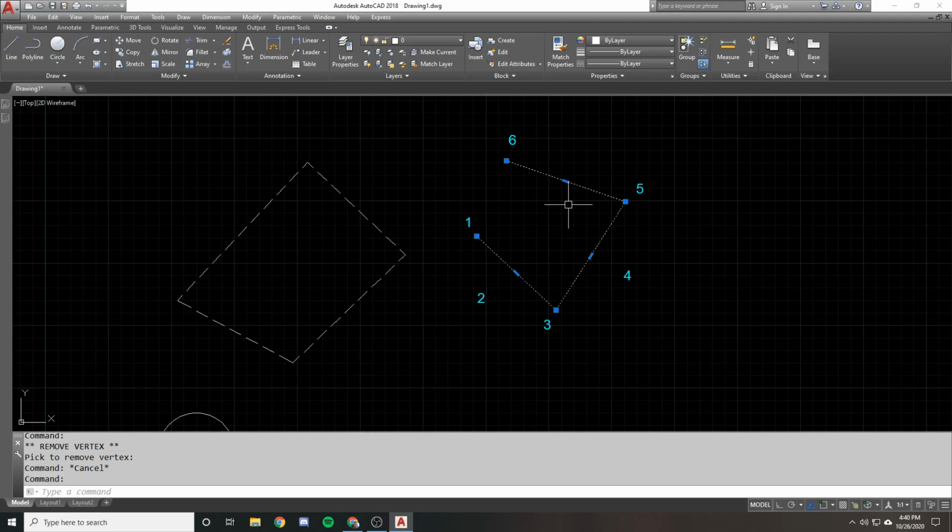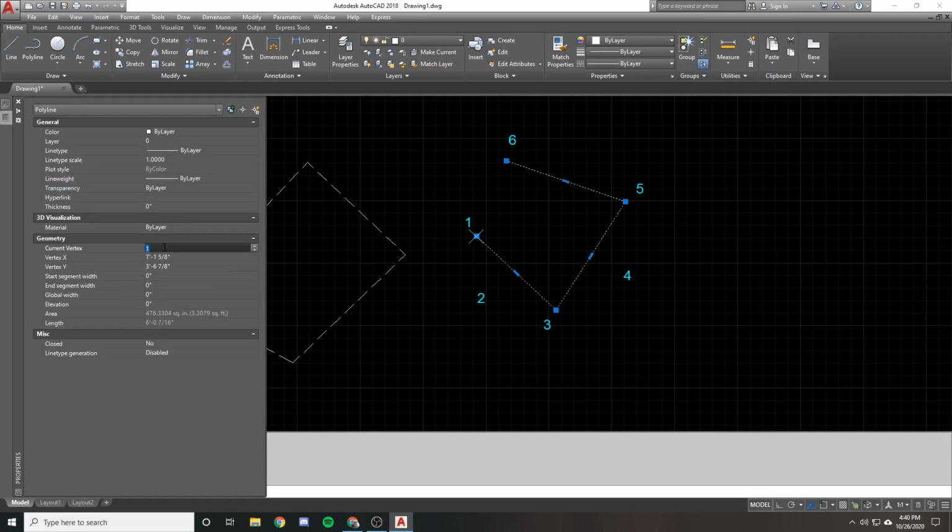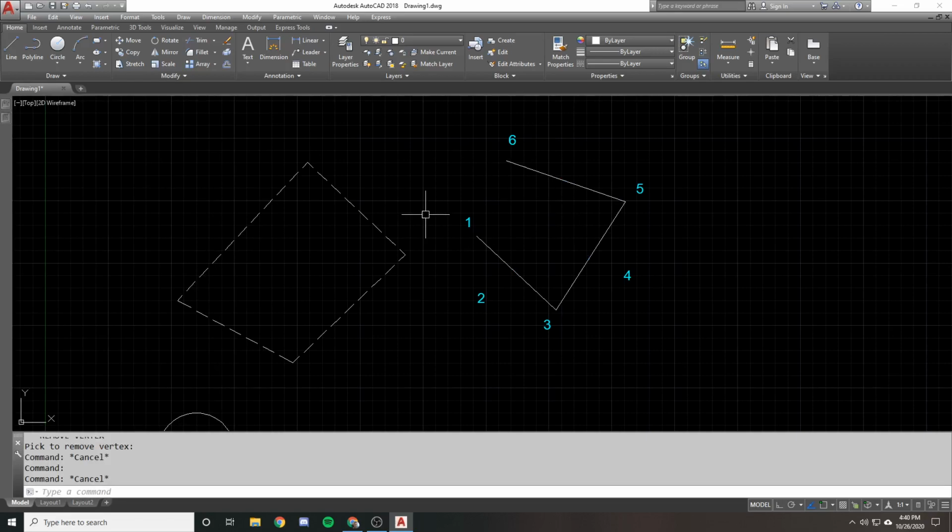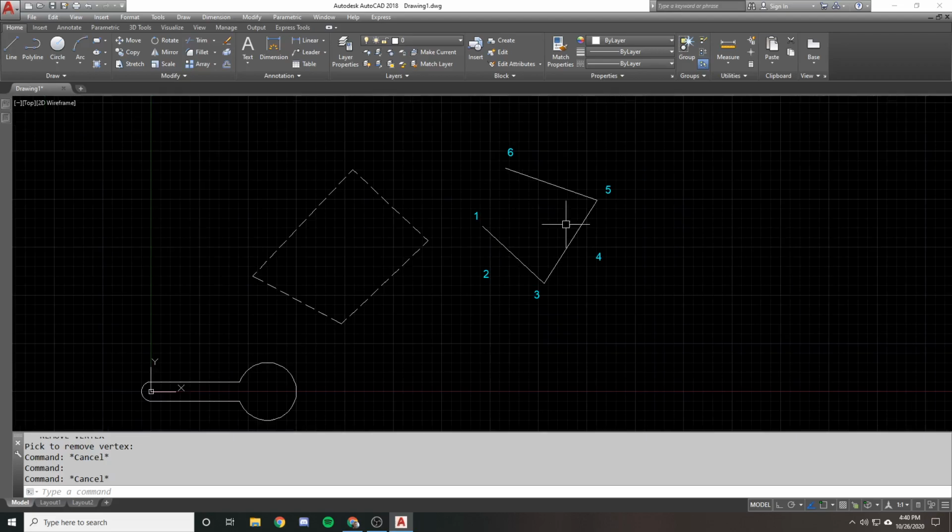The downside is you won't really know what the direction of the polyline is outright. You're just going to have to select it, see where your vertex 1 is, and start kind of mousing upward, clicking upward here so you can see the direction that they go. So if you know the direction of your polyline, you know the direction that you can insert your vertex. Okay, so that's running through all the options of p-edit.